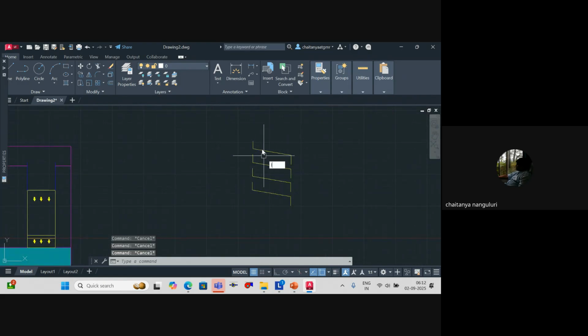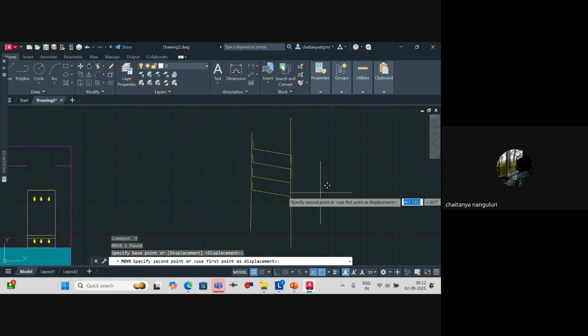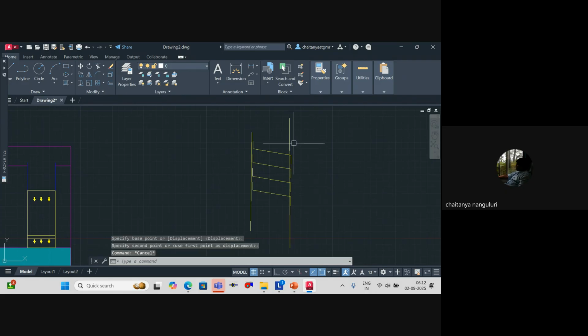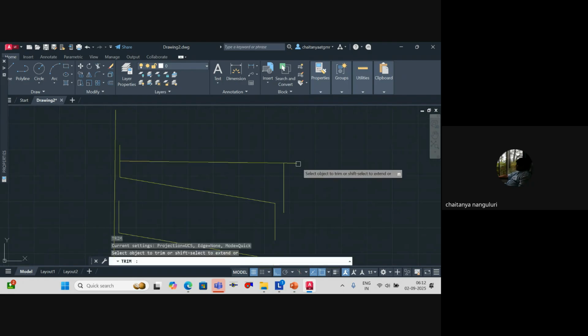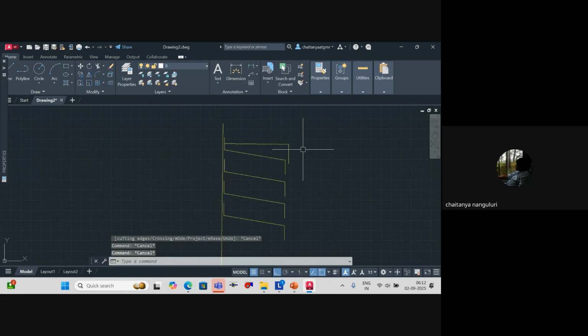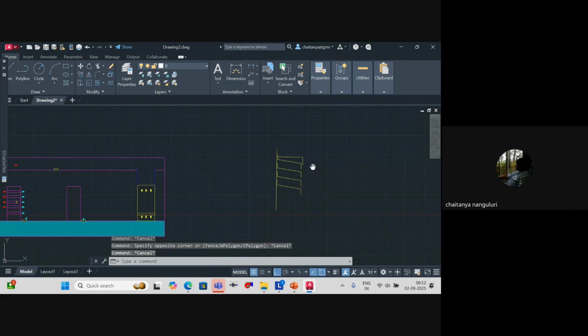Let's say this is your internal wall and this is your external surface. The right side is your external. So when you have this external, do you think any rain or anything can enter through this particular one? This is the total section you have. So automatically, if rainwater enters through this angle, again it will fall back. You agree? So inherently we design it that way.